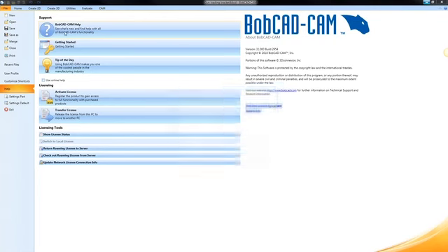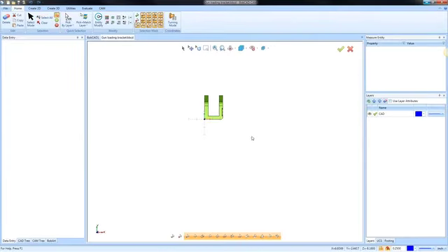You can set them up for your most common features that you guys use. All right, so a little tip there: F1 through F12, set up your common features. Control 1, Control 2, Control 3: top, front, side.